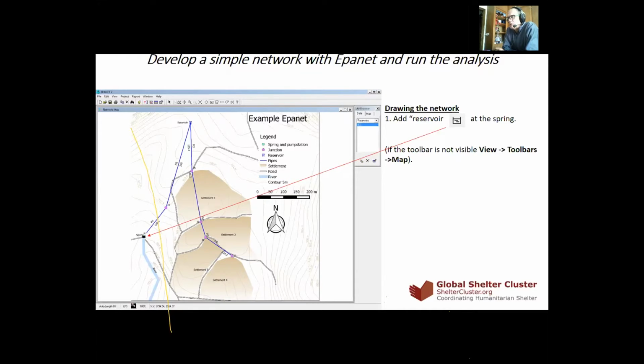And you have to activate the names of the junctions, pipes, tank, and reservoir, so that when you insert them, you can type the right name as in your Excel file, so you don't mix up the elements. In GIS it's easy to display the names. In AutoCAD it's also easy, but maybe a little more complicated, at least for me.